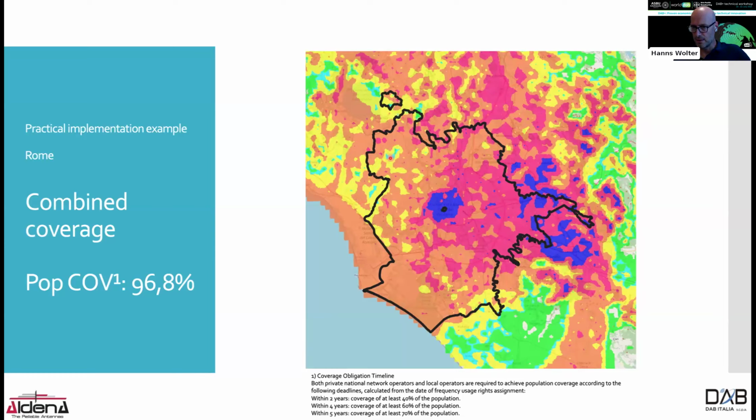Probably the car will work anyway, because what we see is that cars currently work with about 35 dB microvolt at 1.5 meters, but we do not consider this area covered. But now the interesting part, what happens if one of these three transmitters fails?